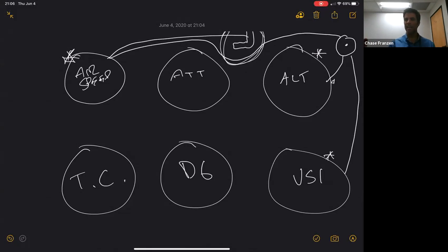That's really kind of complex and theoretical, so we call it airspeed. It's the speed that the airplane feels like it's flying at. And that's why we land at given airspeeds. In a Cessna, our VREF speed is 60 knots. It's 60 knots indicated regardless of whether we're at sea level or at Big Bear at 6,000 feet, even though our true airspeed would be faster at Big Bear because the pitot tube is ingesting fewer air molecules. So that's the way the airspeed indicator works.